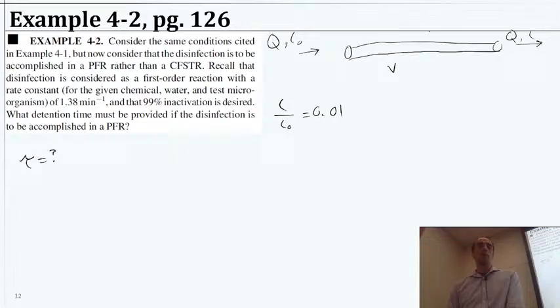So remember that the way we define a plug flow reactor is we take some really thin slice, it's really small width here, and we say that little reactor is well mixed and at steady state. And then you have flow going through it to the next one.